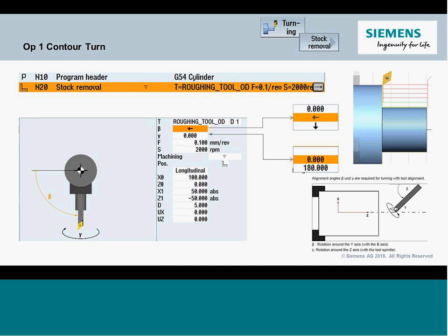That's going to let you drive the orientation, and the system's automatically going to manage it. What happens is this cycle, on the tool change, would plot the orientation angle that I want to rotate to, then go to the start point and begin machining. So that wouldn't happen after the tool's already been positioned down. And we're just going to be driving that base orientation of the turning tool. So here, we'll probably do it at a B0 location and machine it, and then we can flip it around so you can see that. So let's add this into our program.